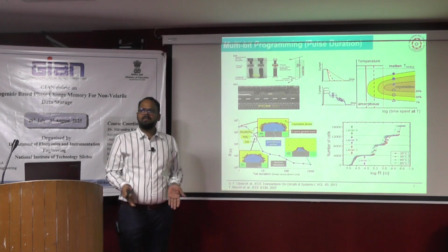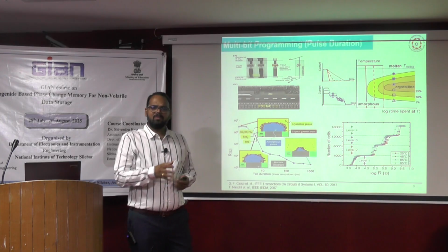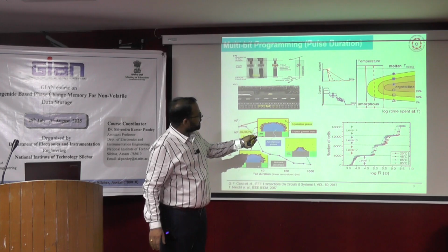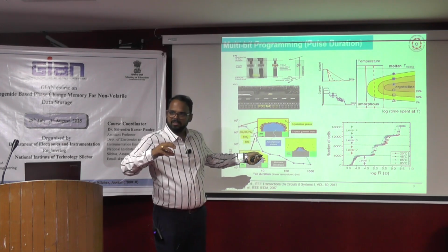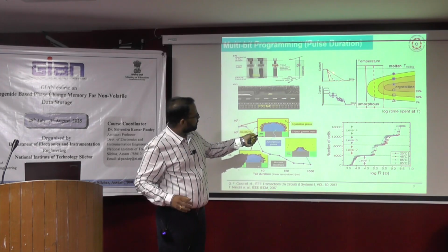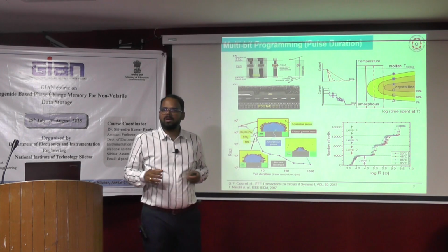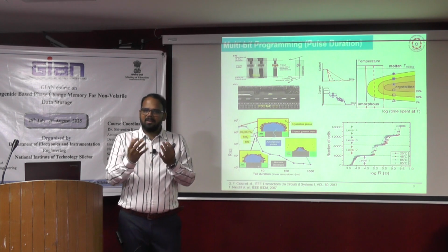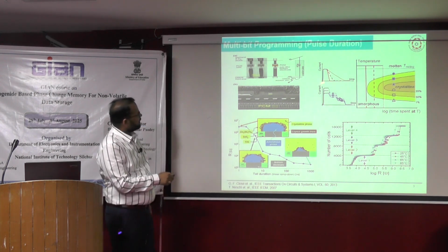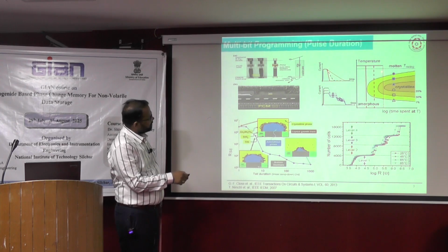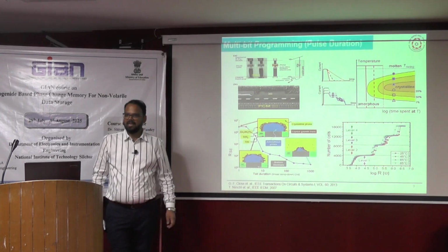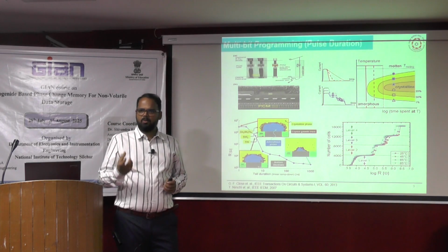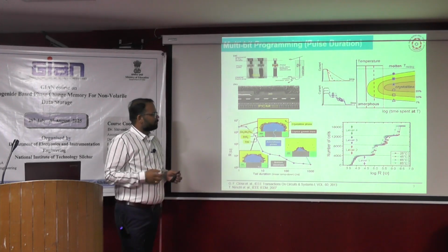This is as simple as heating up and then slowly cooling down. You heat at a particular point and slowly remove your voltage, or your programming pulse. The slower you remove it, the more time the material gets and the more ordered it becomes. Here, when you remove it quickly, it does not get much crystallized. This is the way by which you can identify the appropriate programming technique.